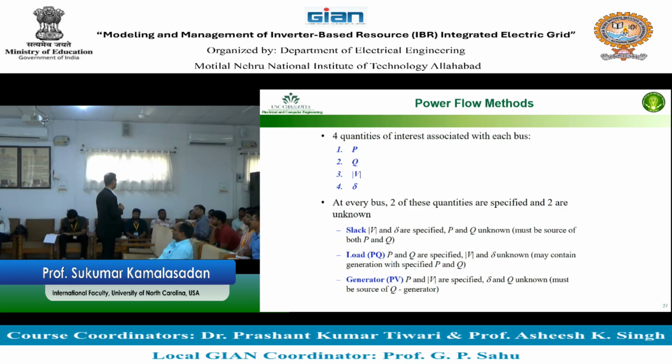Governor is controlling... The governor is not necessarily controlling frequency. The governor is controlling speed and the power coming out from the generator based on the speed. Who is controlling the frequency? All the layers together, load frequency control and everybody together.